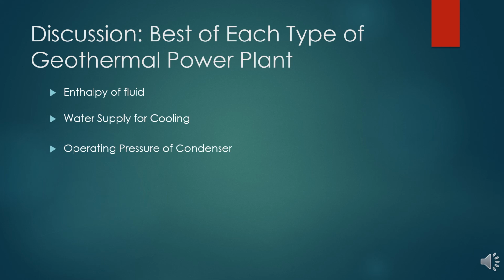Having a large cooling supply of water can also help efficiency, since this large supply of water can reduce the mass flow rate of cooling water required. This is accomplished since a large reservoir of water usually contains water at a lower temperature than which a cooling tower can provide to the condenser. It can also provide the benefit of not needing a cooling tower, such as the geothermal power plant in Guadeloupe.